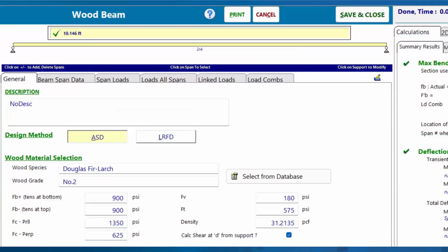So as soon as we finish those very quick approval steps, the calculation seamlessly loads into ENERCALC. And now we actually have span geometry. We've got preliminary section size and material properties all set up and ready for final design. Because we previously had already assigned a material, we got the section size from the name of that type that was already on that Revit element, and now we have a calculation that's ready to interact with.